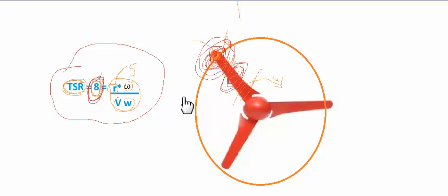Now if this element has the tip speed ratio of 8, we can design twist for it, and as we saw in the triangle, we can easily calculate the tip speed ratios of each and every element along the blade, right?